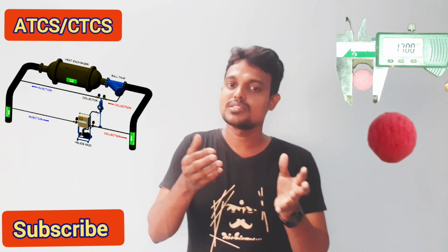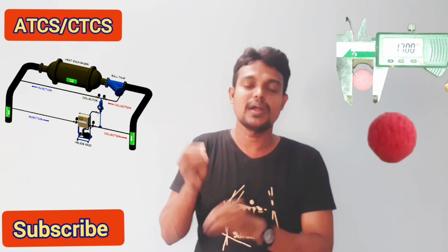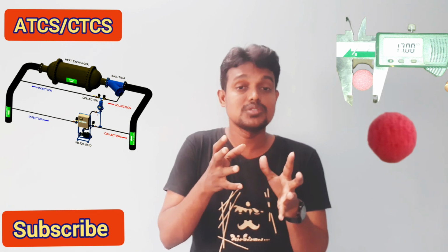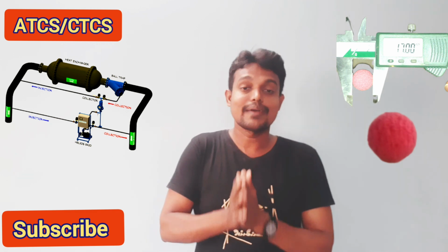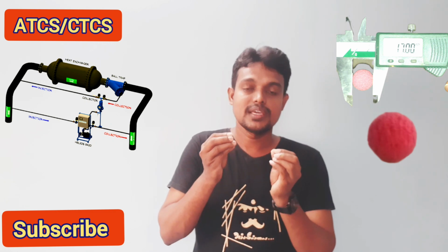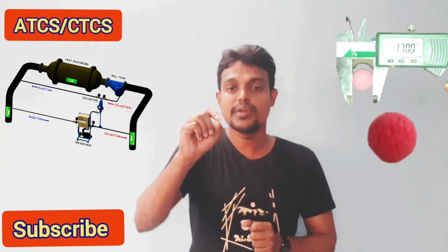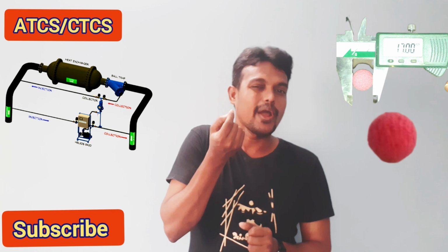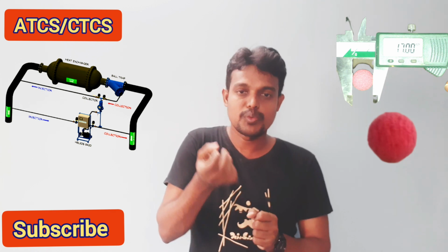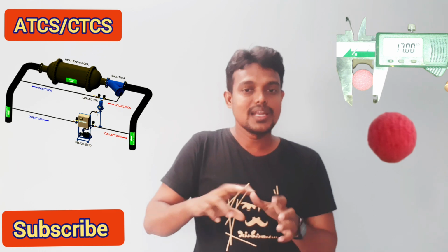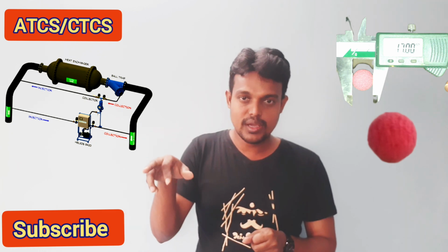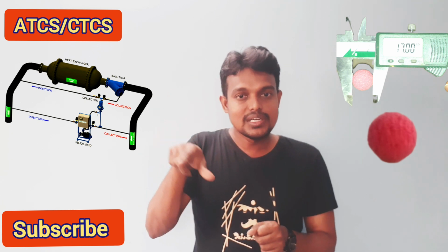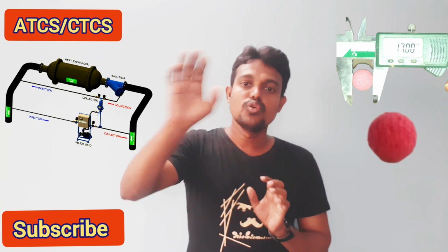Now I have told the working principle of the system, and I just want to add another point: how to choose the sponge ball, the natural rubber sponge ball. For example, if the size of your condenser coil tube is around 20 mm, your sponge ball should be less than 1 mm, or less than 0.5 mm, smaller than that. If you use a sponge ball less than 0.5 mm, it will not get stuck anywhere in your condenser coil, and it will descale your condenser coil throughout the line.